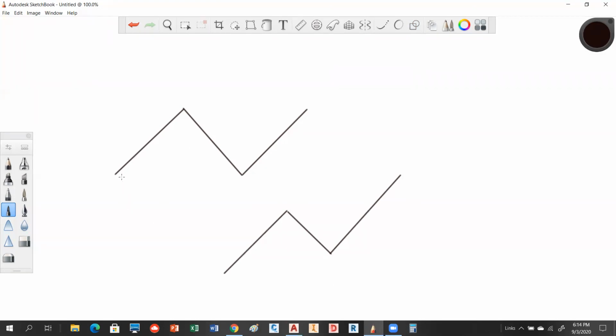The other thing, in AutoCAD, these guys right here, those are called endpoints on lines. So in a polyline, these guys right here are not called endpoints. They're referred to as vertexes. So that's a vertex, that's a vertex, that's a vertex. Polylines also have a definite direction associated with them. So there's a starting vertex and an ending vertex, and so it knows which direction is going on with it. Lines really don't have that. They just have two endpoints.